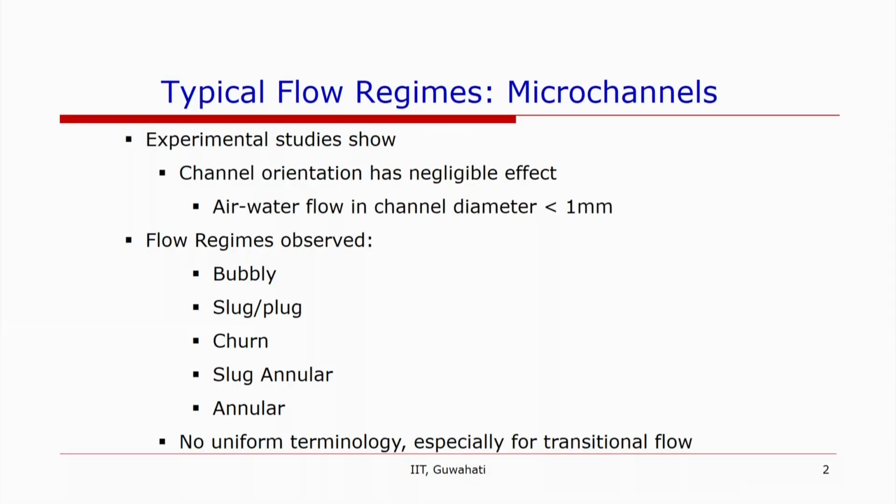So, in this lecture we will talk about flow regimes, what we were discussing in the previous lecture, but now we will come to the flow regimes in small diameter channels. So, briefly we looked at the Eötvös number or bond number criteria that can be used to define the critical bond number at which one can start looking at the channels where you can expect the micro size effects starting to show up. And there were 3 different criteria that we discussed in the previous class.